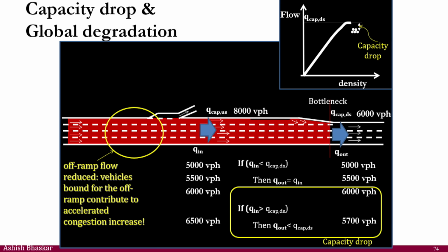People use that to understand, depending on the depth and length of the side friction, what kind of impact there is on capacity drop. For that, generally people do microscopic modeling, and develop some kind of reduction factor and those things.